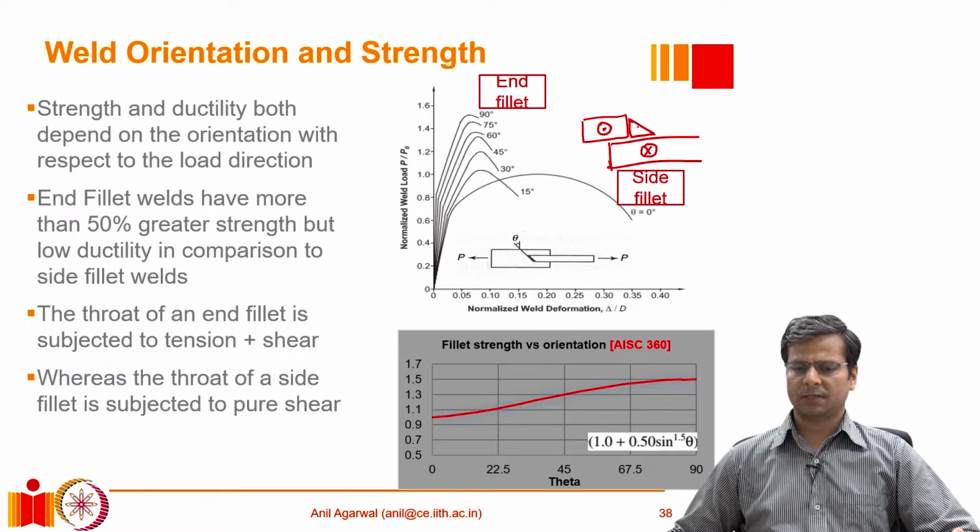In this situation, the stress state is relatively simpler. There is a shear at this interface and also a shear at this interface. So this situation is very different from what I had just discussed before. In such a scenario, we have got shear on both sides, and wherever there is the smallest interface, the weakest point, that is where the failure would take place, and we can just check the shear force demand there, which will again be dominated by shear stresses.